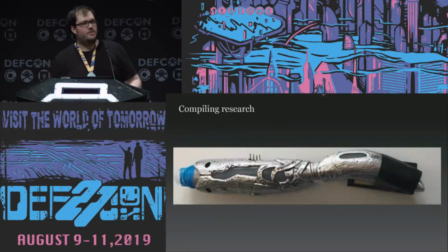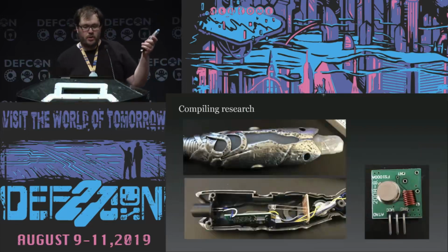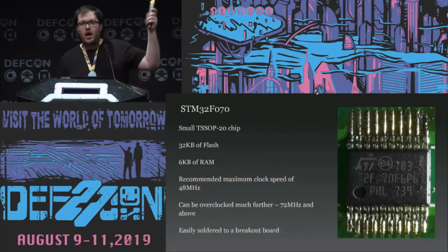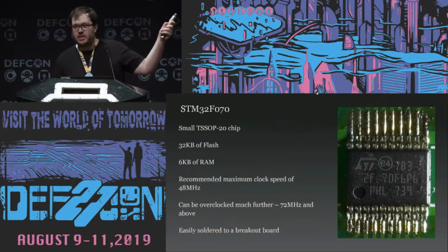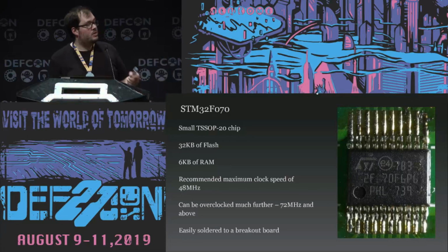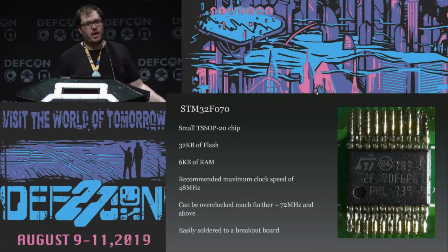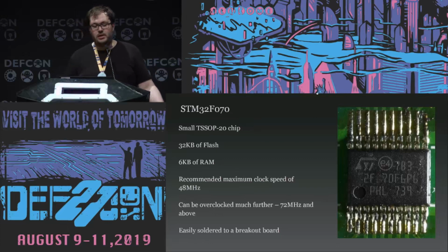So I made this. It's a sonic screwdriver, a toy one, which is now full with all the tools that I've just talked about, and I've got it with me. It's got 4 modes so far. It's got traditional NFC tag fuzzing, transmission of ASK data. Basically, it's got an ASK transmitter in the handle, which transmits any authentication being sent from a reader to the device, allowing someone with a laptop and an SDR far away from me to get the authentication keys back and dump the data.